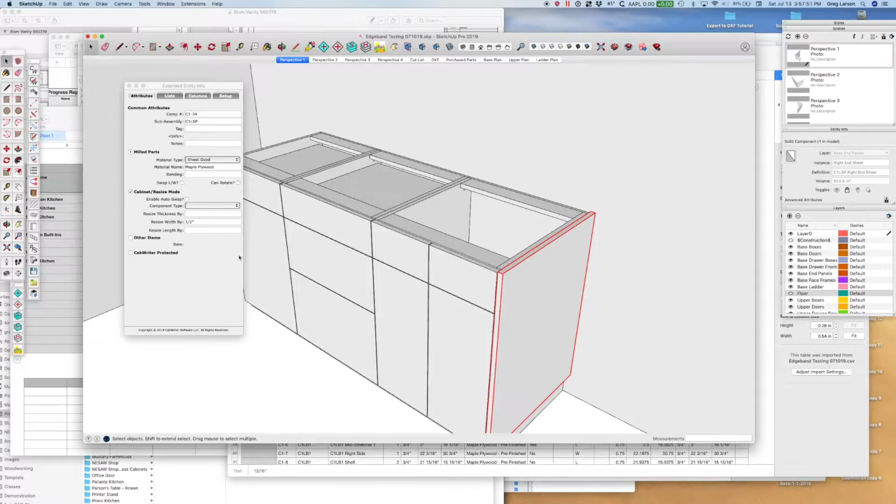But what if I wanted to add edge banding to this now? I would want it only oversized by 3/8 of an inch, so that when I added that other 1/8 of an inch on, it would be 1/2. So I can just select this part and manually change this to 3/8 of an inch. And when I rerun my production reports, it would show up 3/8 of an inch smaller on the cut list instead of 1/2 an inch. So I can do this as a combination of manual. I can override one on a case-by-case basis in the extended entity info window.